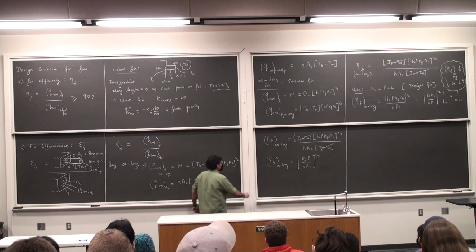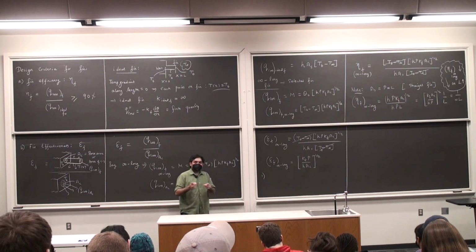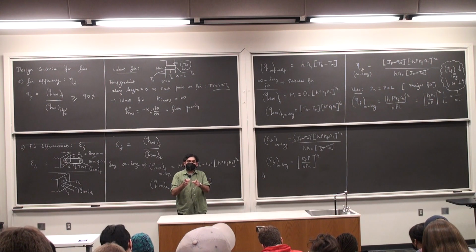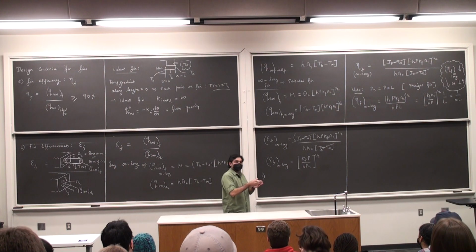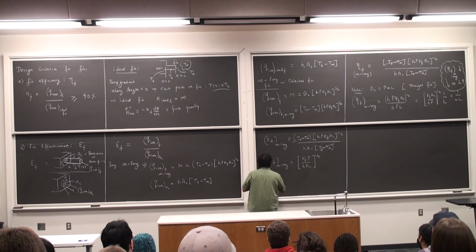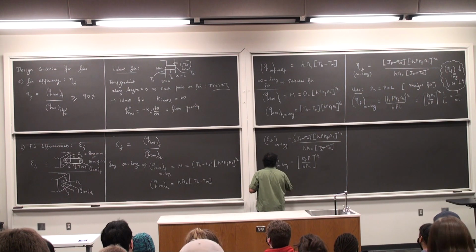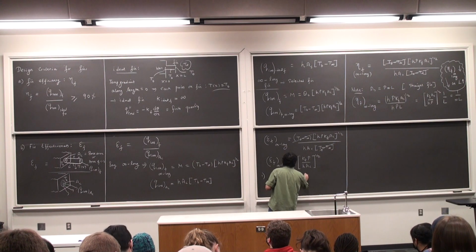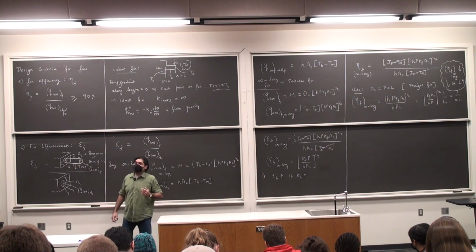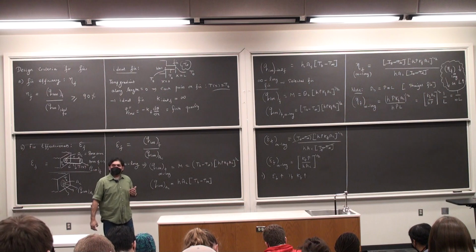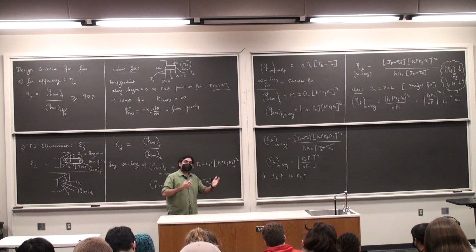First thing. To increase the effectiveness, what should I do? I should increase the thermal conductivity of the fin, because K is a parameter right there, starkly sitting in the numerator. So epsilon f increases if K fin increases. This is one reason for having a very high thermal conductivity. And the added benefit of that is also that the temperature gradients are reduced.